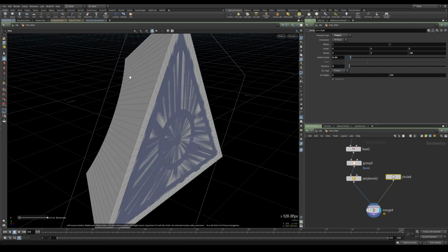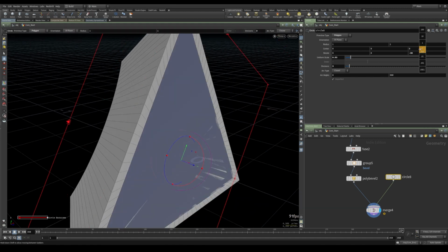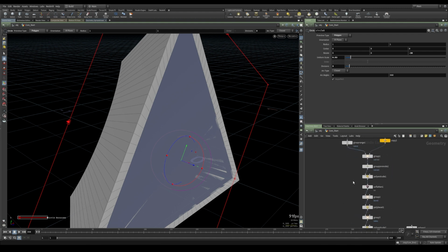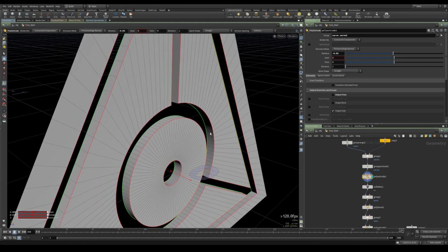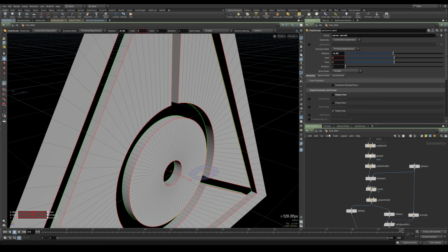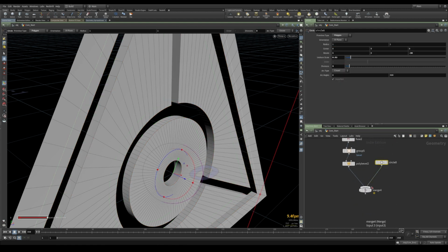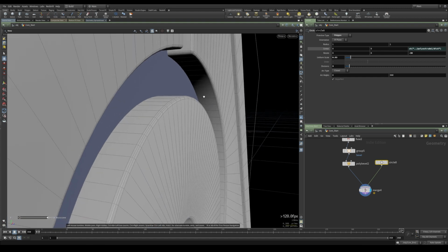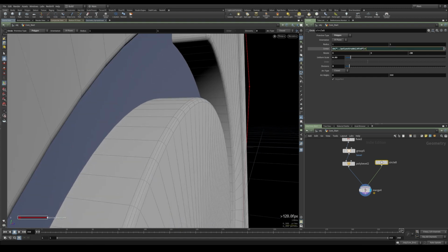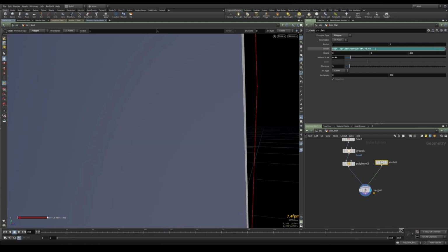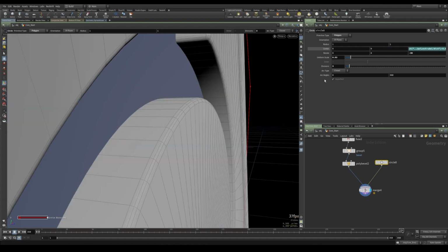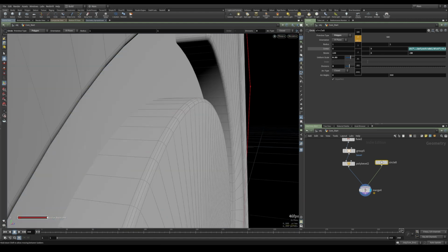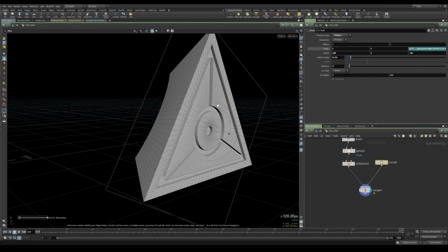And also we want to offset it on the Z, and instead of doing it manually, we can use the first poly extrude distance, which is this one. So let's copy the parameter, go back on the circle and paste relative reference here, and maybe give it a little bit of offset. So let's say plus 0.02 and maybe another 0.002. So it will be slightly offset, and also rotate it by 180 on the X axis.